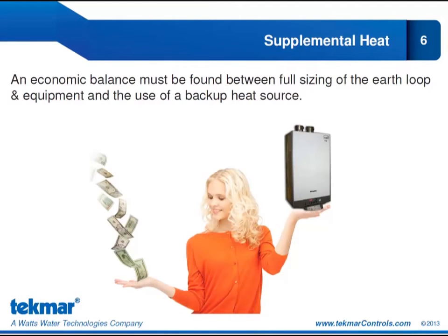When we're considering adding a backup heat source, what we're really doing most of the time is trying to find the economic balance between full sizing of the earth loop and equipment and the use of a backup heat source. The backup heat source allows us to downsize the earth loop and downsize our equipment, which will lead to significant cost savings. But then we have to account for the fuel costs of operating our backup heat source.